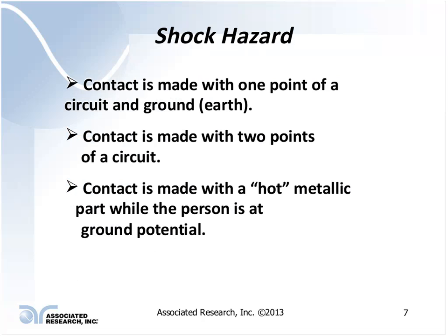So if you're grounded and you contact a circuit that is energized, you've completed that path and current will flow through you to that available ground path. And this is going to result in a particular hazard. The severity of that shock hazard is really going to be dependent upon several factors, which we'll talk about in a few minutes.